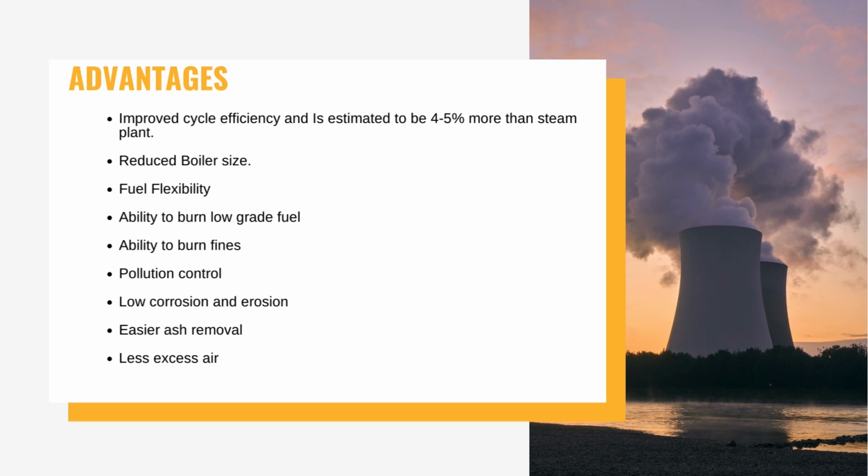Less excess air, higher CO2 in flue gas. The CO2 in the flue gases will be of the order of 14 to 15% at full load. Hence, FBC boiler can operate at low excess air, only 20 to 25%.